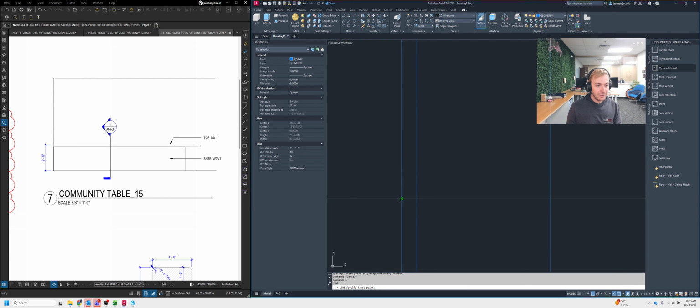Let's go ahead and start with some more construction lines for the vertical dimensions. So right away, we know that our height from floor to top of counter should be 2'6". So we're going to offset this line from the floor up 30 inches. That's our countertop height right there. All right.